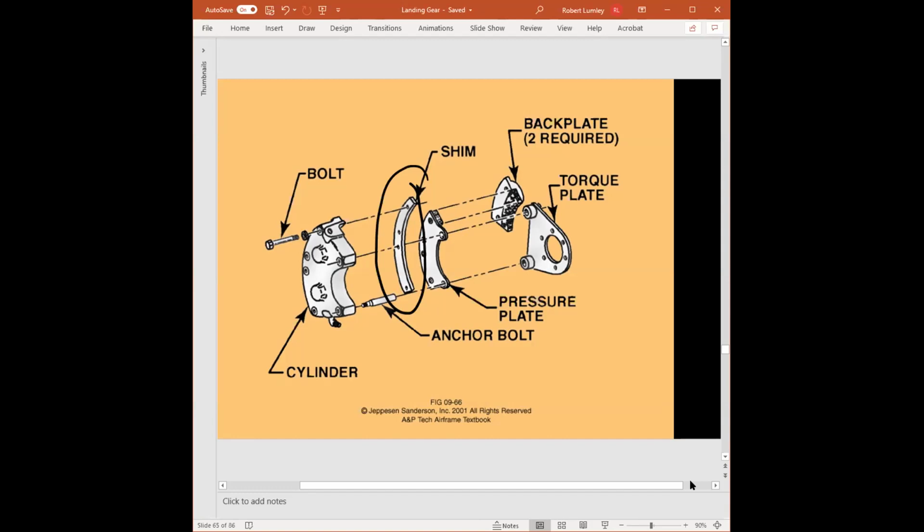Well, let's say we replace a worn out disc with worn out pads. All of the wear surfaces are worn beyond limits. So we replace with a brand new disc and brand new pads. What's crazy is in that setup on some aircraft, there's a shim that has to be installed for it to go together, because the disc with new pads can be so thick that there's not enough space, and if you do not use the shim, the brakes will drag.